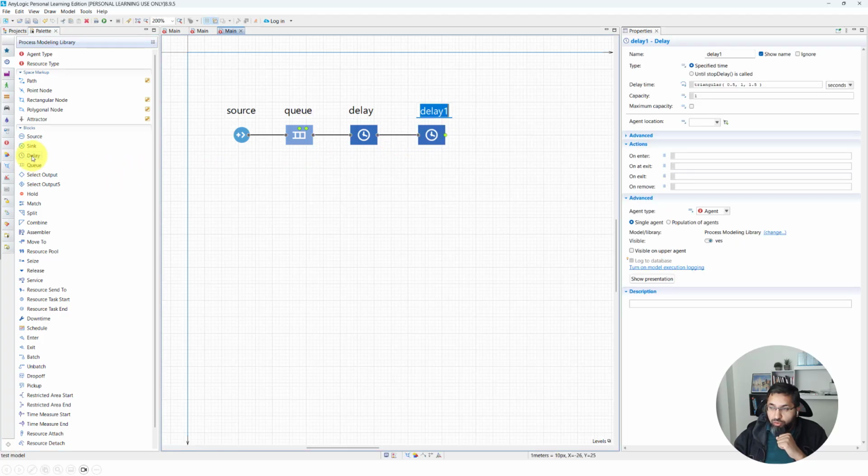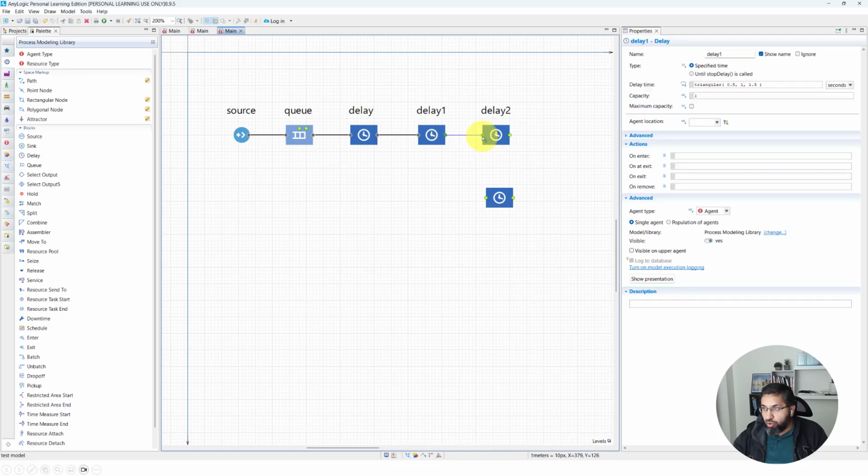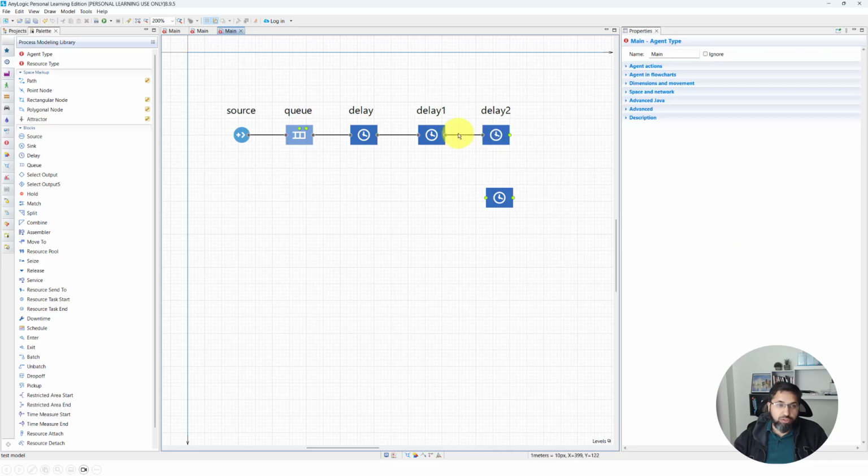Now I'm going to show you what happens if it doesn't. Let's say you put it somewhere here, it doesn't connect automatically, and then later you move it up. Well, it did connect automatically, but let's say this was not here. How do you connect manually? You double click this green block, you go here, and then because you're ending here, you double click here, and it builds that connection. Always double click on a green circle, go to the next green circle, double click, and that can build the connection too. Okay,